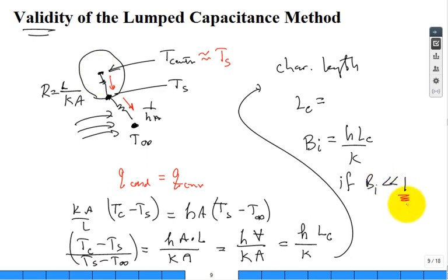This always brings up a good question. We just talked about the exponential. When's the action done when you have this decaying exponential? 5 time constants. All right, here, what's much, much less than 1? And that's a judgment call. If somebody said 2, is 2 much, much less than 1? What would you say? No, it's not. How about 0.2, 20%? Is that much, much less than 100%? No. Most people would say no. How about 0.02? Yeah, I mean, say 2 pennies compared to $2, right? You're just trying to put some common sense on this. 2%, yes, 0.002, definitely. So somewhere in between 0.2 and 0.02 is the cut, and most people would say about 0.1, somewhere in there.